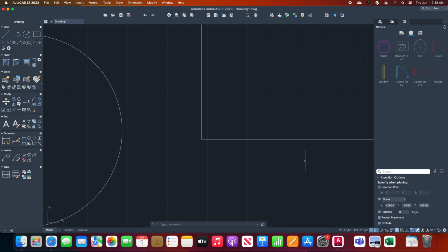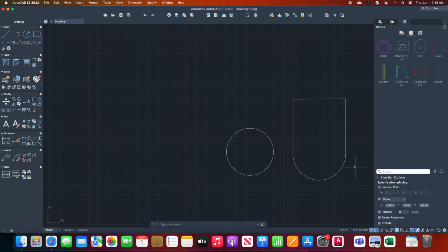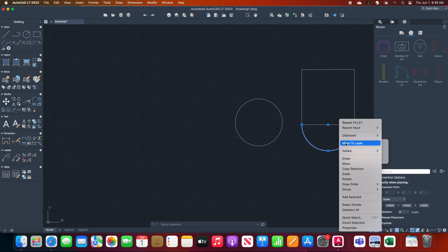Okay, something's not perfect, but I want to fillet that part, radius 6 inches. Now I fillet that part and that part. I guess more than giving it a 6-inch circle, what it's doing is, if you connect opposite ends, it's just joining it with an arc, whether it's 6 inches or not. We can measure it, but that was one of the lessons I was going to do. So saying that from this point it's 6 inches, 6 inches, 6 inches, 6 inches all around.